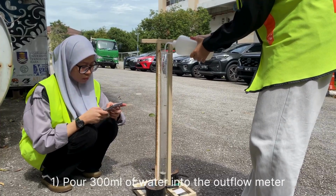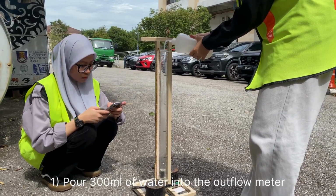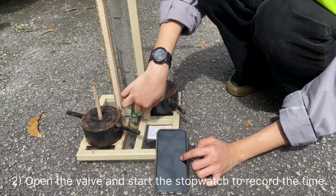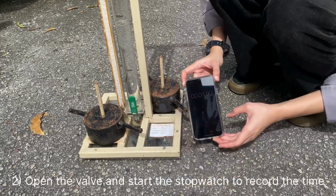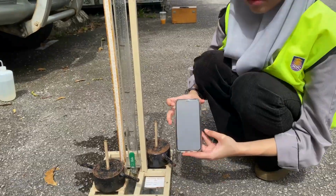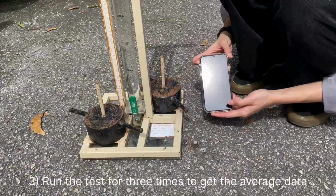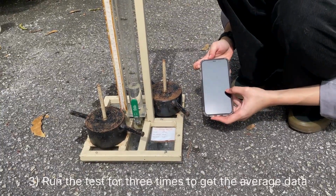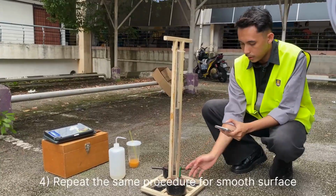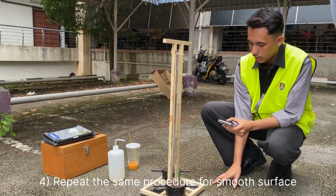Pour 300 ml of water into the outflow meter. Open the valve and start the stopwatch to record the time. Run the test 3 times to get the average data. Repeat the same procedure for the smooth surface.